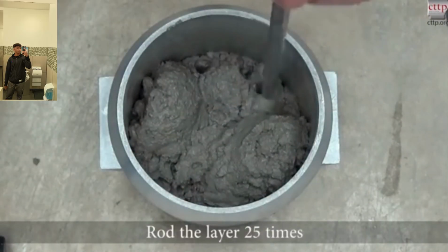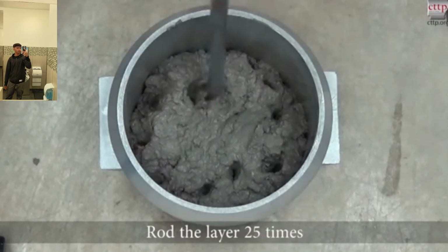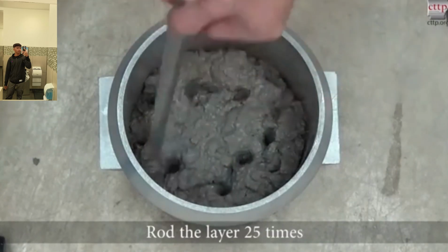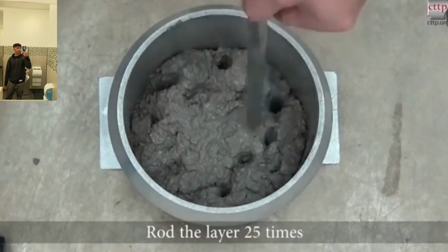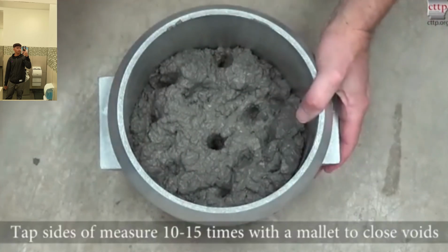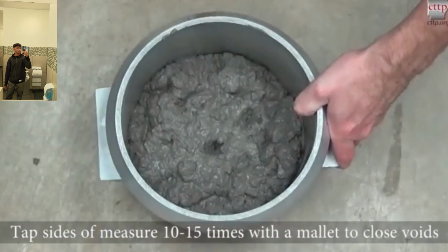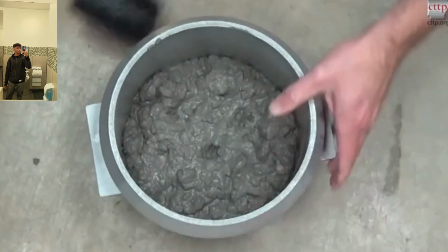Rod the layer 25 times. Tap the sides of the measure 10 to 15 times with the mallet to close voids.